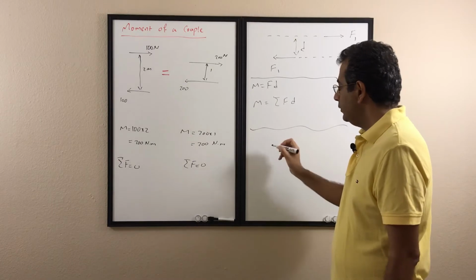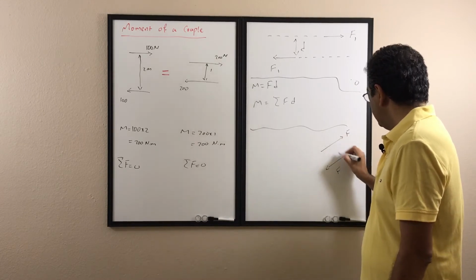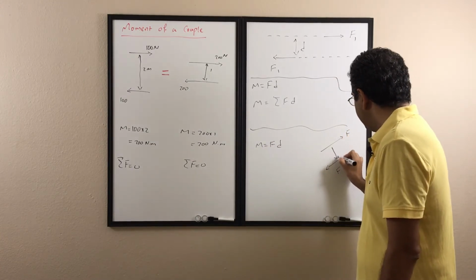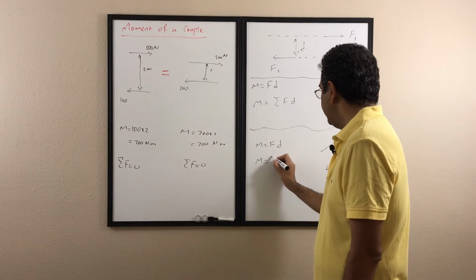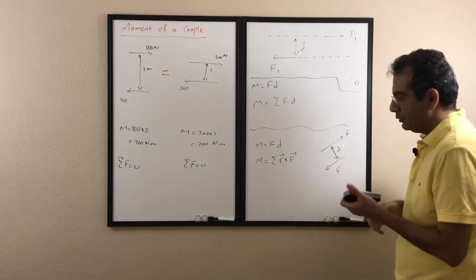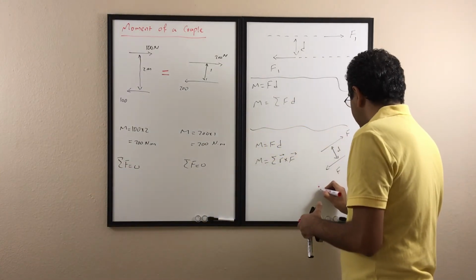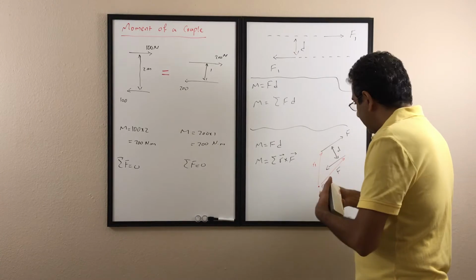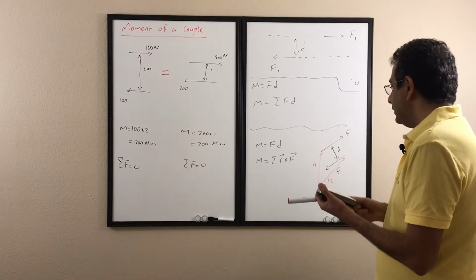The same thing in 3D. If we have two forces and we know the normal distance between them, although it's 3D, the magnitude is again F d. Otherwise, we can go ahead and find R cross F. If we don't have the normal distance between two forces in 3D, just assume a point here, and these are going to be, for example, R1 and R2, then calculate the moment of each of the forces about that point and add them together.